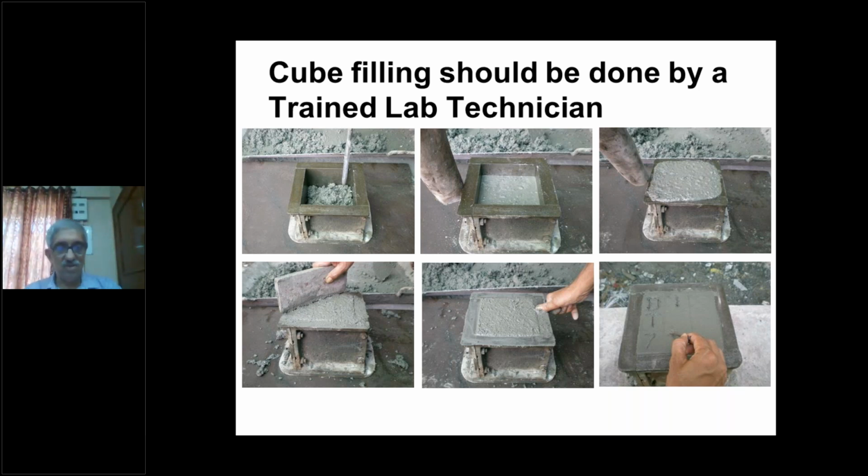Sometimes the actual concrete is not good, but the cube gives good results if the technician is not correct. So it's very important to have a standby trained lab technician also at the site. So in case one person is absent, the other person takes charge and does an equally good job.